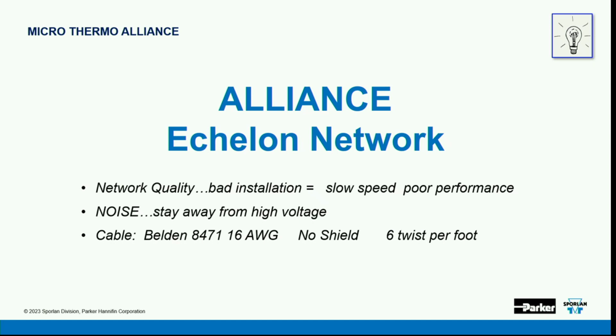Some VFDs are notorious for being very dirty, okay? They put a ton of noise on the system. Keep the network away from that. Isolate it with a router or repeater or a lifesaver device that we make if you have to. But keep the noise off the system.